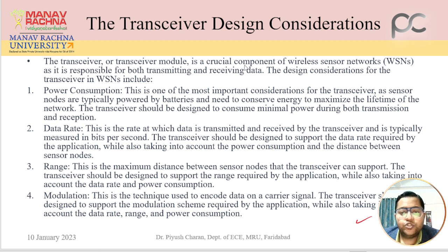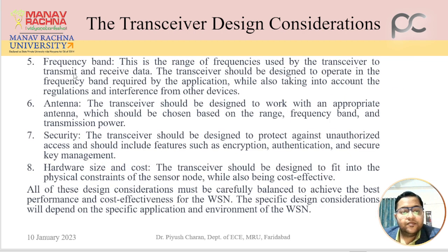It is a very crucial component of wireless sensor networks, as it is responsible for both transmitting and receiving data. Design considerations for the transceiver in wireless sensor nodes include power consumption, data rate, range, modulation, and there are others also: frequency band, antenna, security, hardware size, and cost.